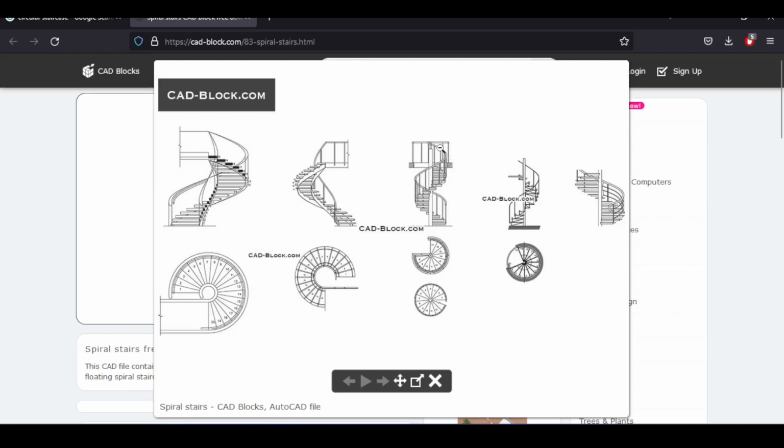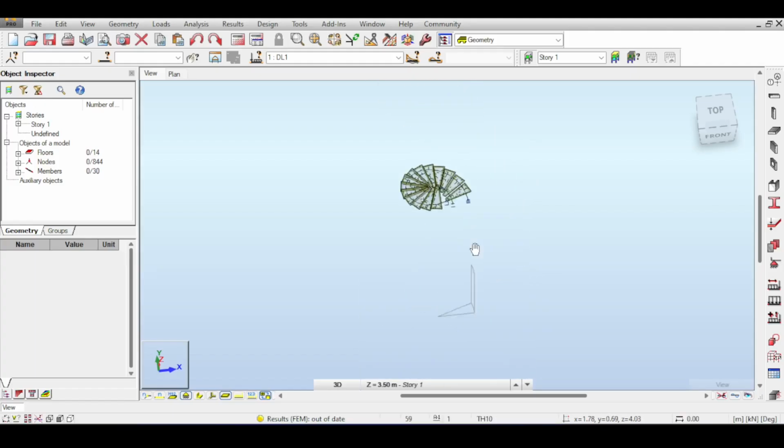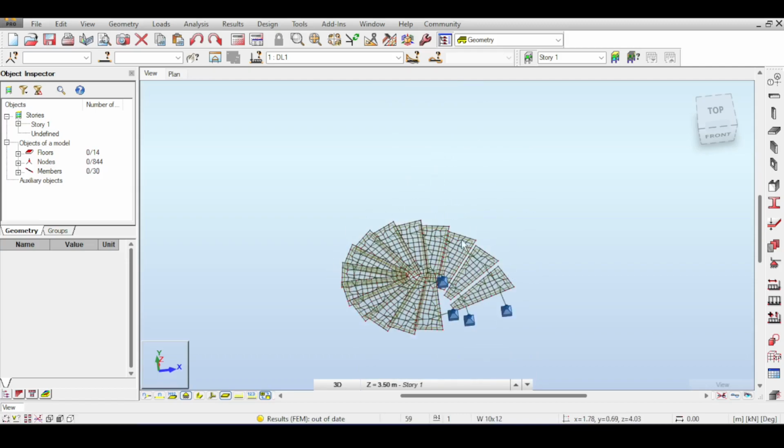Because for something to carry, it must have a huge stiffness and must have adequate supports. I don't see it supporting with anything, I see it supporting on the stair, on both sides. Because it's not supported well and has low stiffness, I think this is not a carrier, but a carried entity. So you need to take this into account. Also, you need to take the terrace into account in your loading by applying forces on the edges of the staircases.